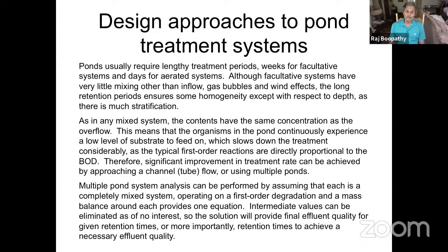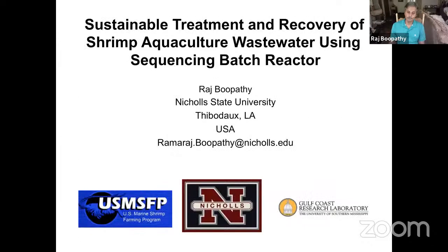So you need to make sure you design, again, depending on how much wastewater is coming through, you need to design the lagoon accordingly, and also the carbon loading and nitrogen loading. So a lot of design concepts go in there when you design your pond system. So I just went through some basic concepts and a little bit of commercial reactors, and then I talked about what is being popular nowadays. Constructed wetlands, assimilation wetlands, and sewage farms are getting popular now.